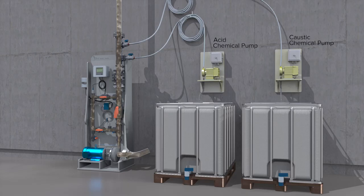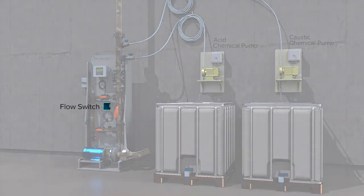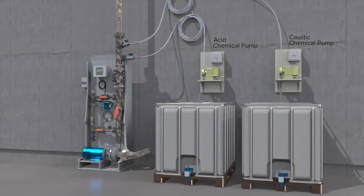Mixing acid and caustic can cause a violent reaction if not properly managed. Because of this, World Waterworks has programmed several safeguards. A flow switch is installed on the pH stand to ensure the chemical pumps can only run if there is flow moving across the probe.